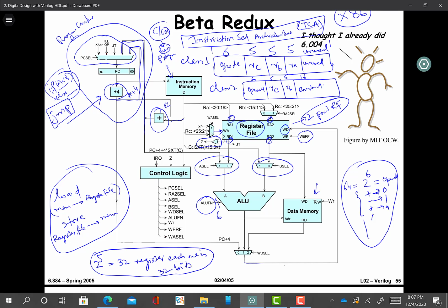With that memory there are two related operations. One is called load, which means you want to load something from that memory into your register file and bring it closer to the processor so that the processor can execute an algorithm on it. Or you want to store, which is the reverse. There is something in the register file which you want to store in the memory. So these are the two basic operations. If we want to store something, this line is coming from here. So write data is coming from RD2, read port 2. Similarly, if we want to load, then we read from here, and this comes to this path, and this is written here. So this is load.